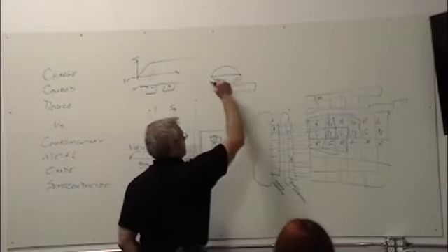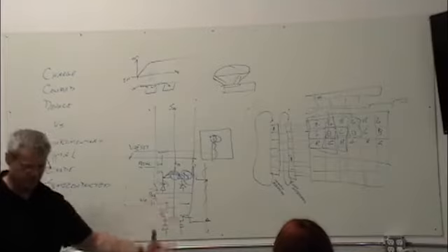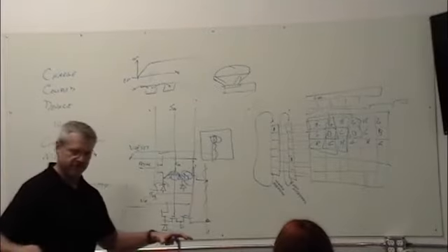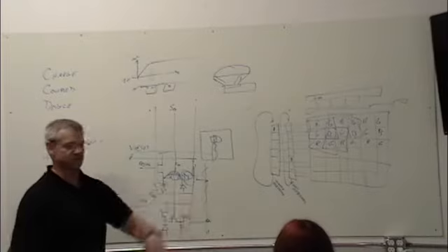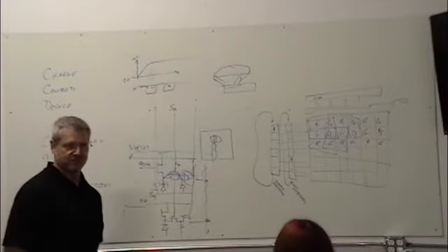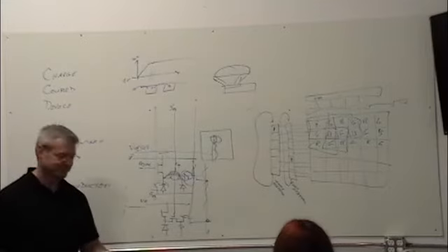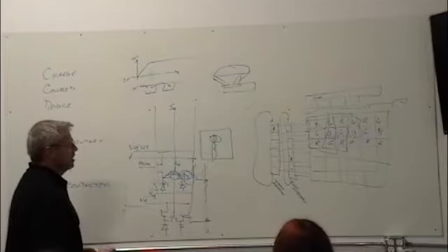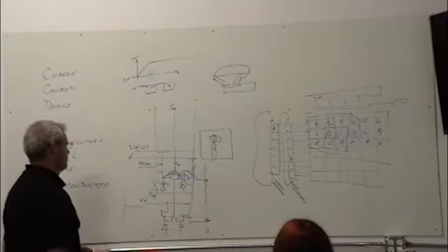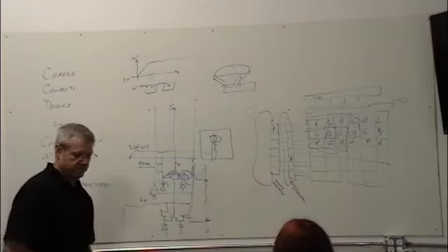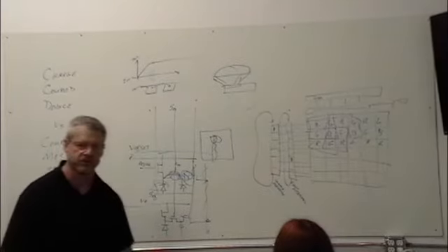It's a fairly easy process step. You do some interference patterns with your masks, and then you do an etch time, and so the mask is thinner in certain places than others. So a given etch gives you a periodic waveform that matches the interference pattern. So they make an interference pattern that looks like a whole bunch of lenses, and then the etch gives them lenses. And the silicon dioxide that they use is clear. That's probably 145% of all you ever needed to know.